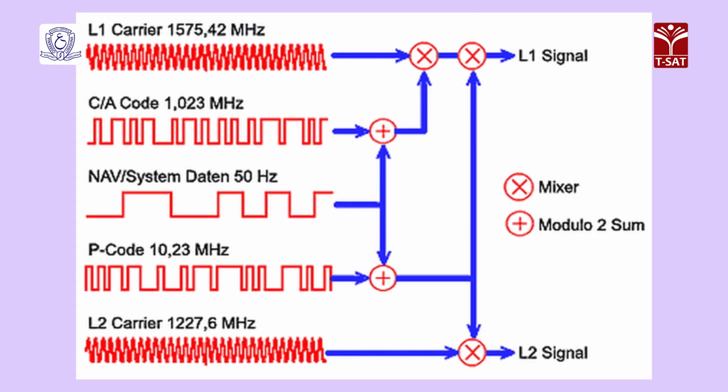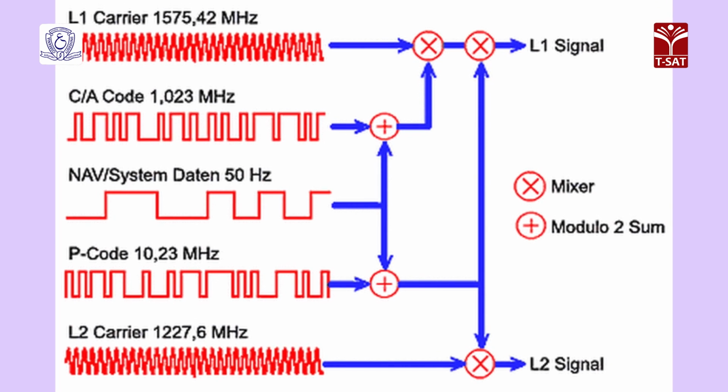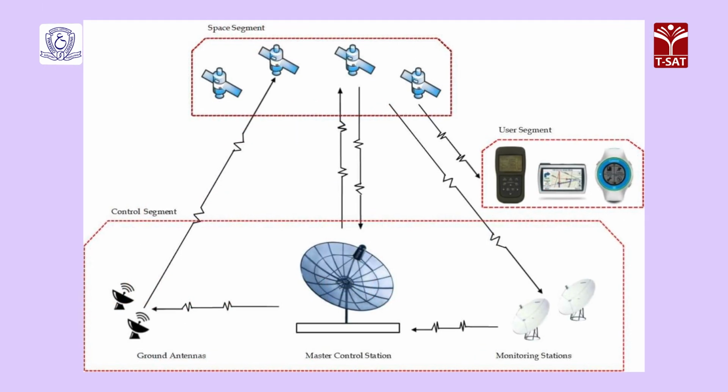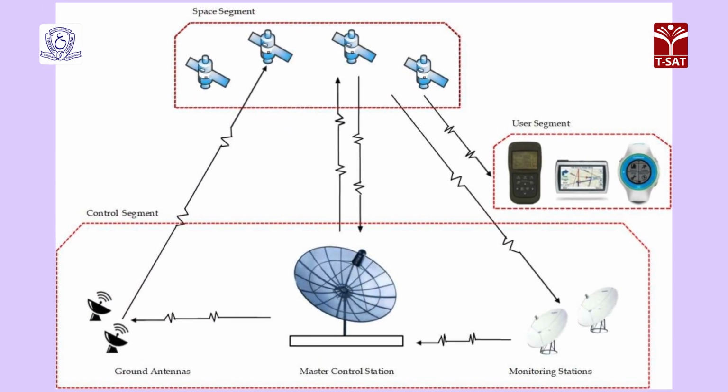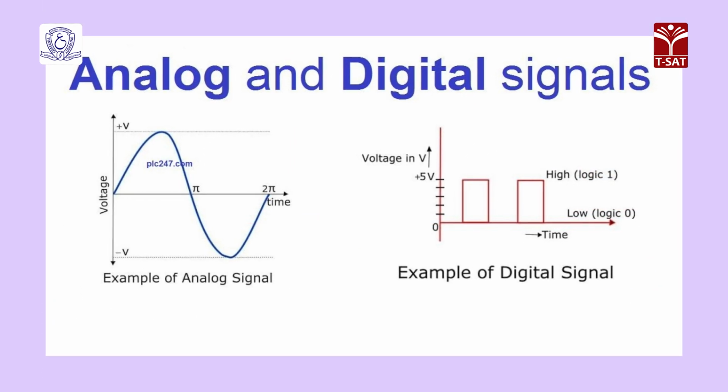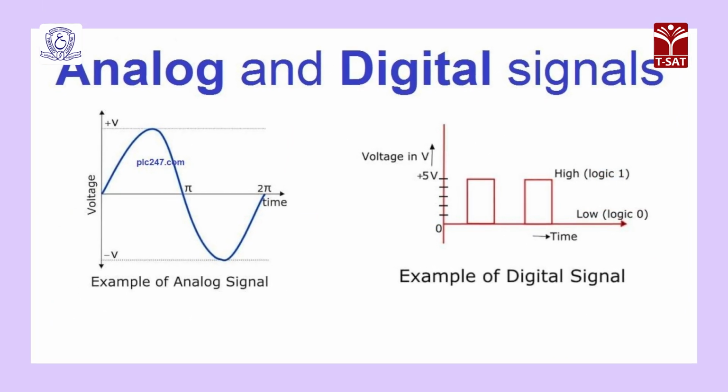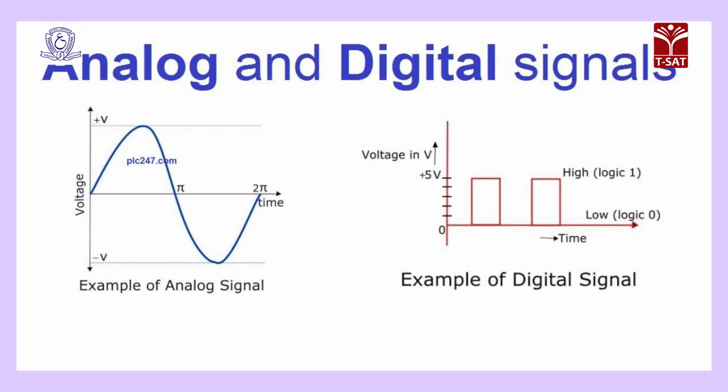Hardware bias errors. There are different types of satellite bias present. Upon signal transmission, the GPS signals on each carrier frequency and among frequencies are imperfectly synchronized due to the different digital and analog signal paths corresponding to each signal.